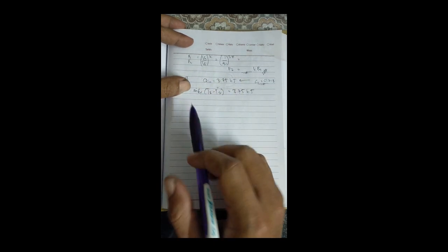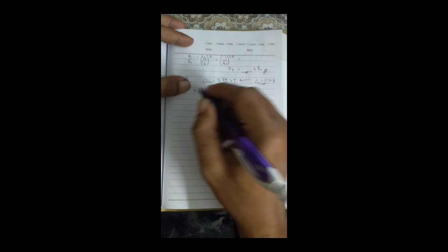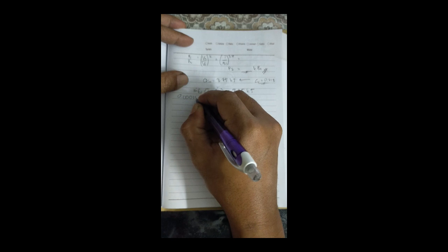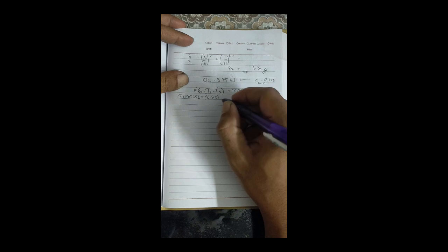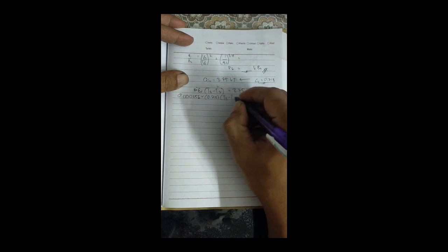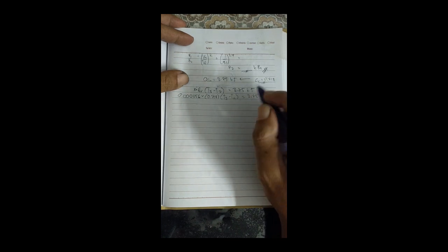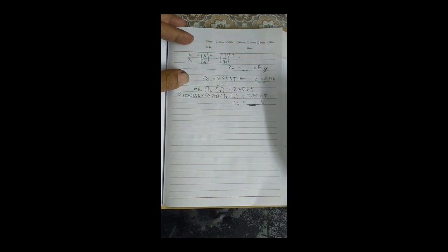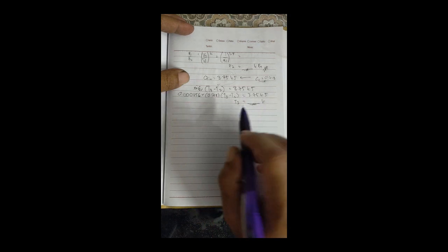CV is 0.718, and mass we have calculated before at 0.000356. So we can calculate 0.000356 times 0.718 times T3 minus T2 equals 3.75 kilojoule. So T3 in Kelvin is quite high. Alright, so we have the temperature.